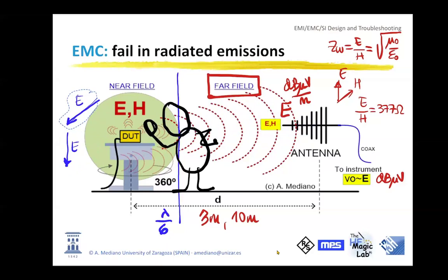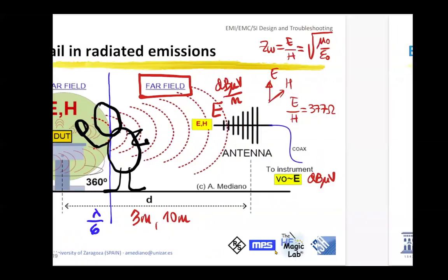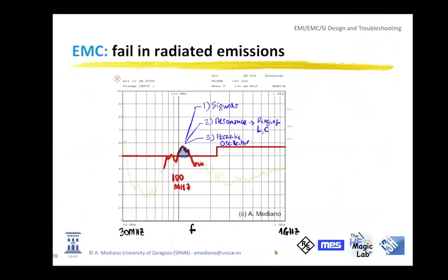Usually this measurement is done in a clean area, in a sealed area, in a chamber, or in an open area test site, trying to minimize the possibility of external noise from the environment or reflections in walls or in metallic structures that are close to the setup.